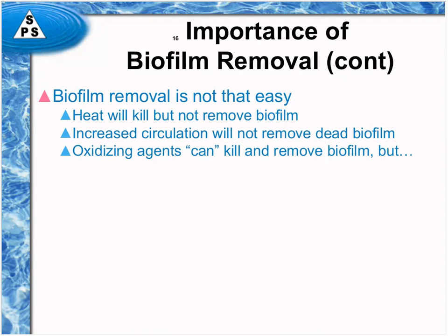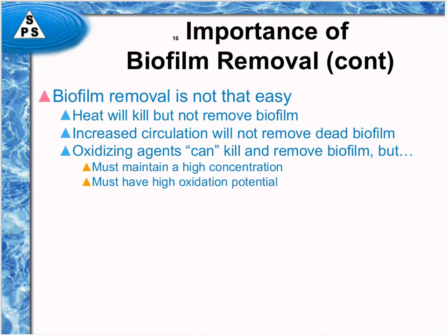Oxidizing agents can also kill and remove biofilm, but you have to maintain a very high concentration, and the sanitant has to have a very high oxidation potential, so it has to be very aggressive, and the contact time has to be for quite a while. And often one, if not two, if not all three of these conditions are not met by the sanitant that's being used, and so you often don't remove all the biofilm with a chemical sanitant.